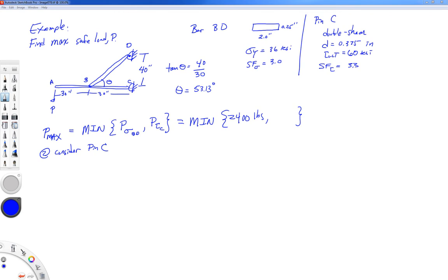All right, so we want to find out how the shear force resultant at C relates to the applied force P. Again, we're going to draw a free body diagram. Let's just draw a new one. We have our reactions, Cy and Cx, and we have our force P that's applied to the structure, and we have the unknown force FBD off at that angle theta. Let's write down our equilibrium equations.